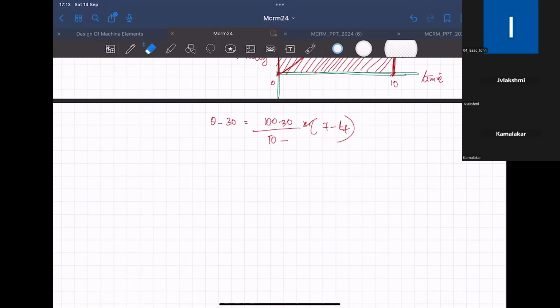Constant non-zero acceleration throughout, that is false, right? Because acceleration will be 0. If velocity is constant, its derivative, acceleration, would be 0 throughout, but it will have some instantaneous infinite jerk at the start and at the end. So that is true, but non-zero acceleration is actually false. Acceleration is going to be 0. And 3 would be: straight line interpolation has 0 acceleration throughout, but with an instantaneous infinite acceleration at the beginning and at the end of the path segment.